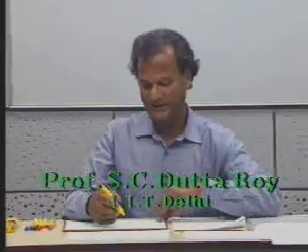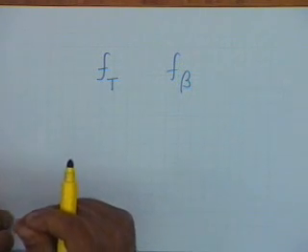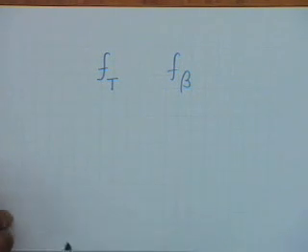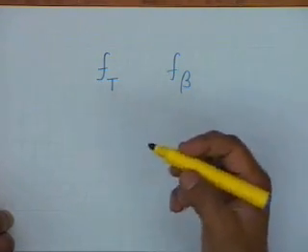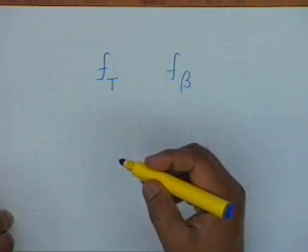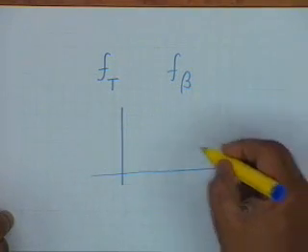This is the 37th lecture on small signal amplifiers and feedback. In the last lecture, I had introduced the terms Ft and F beta for the figure of merit of a transistor, and I explained that if you measure beta, that is the short circuit current amplification factor of a transistor, then beta varies with frequency.